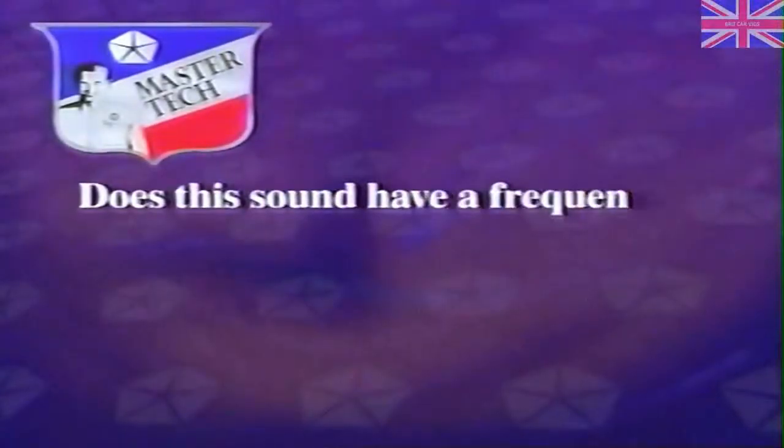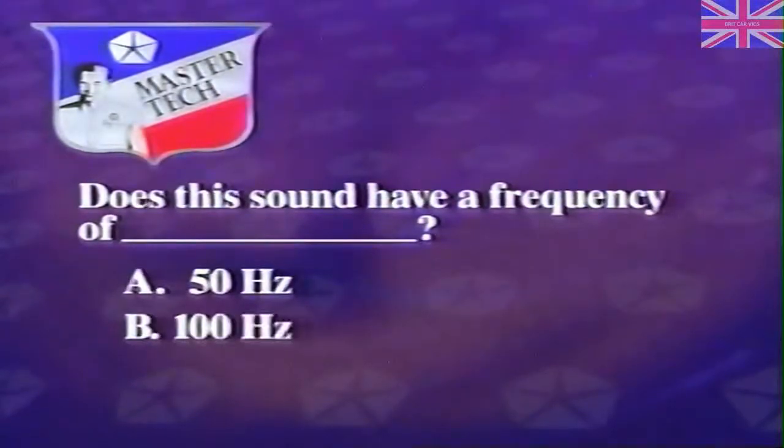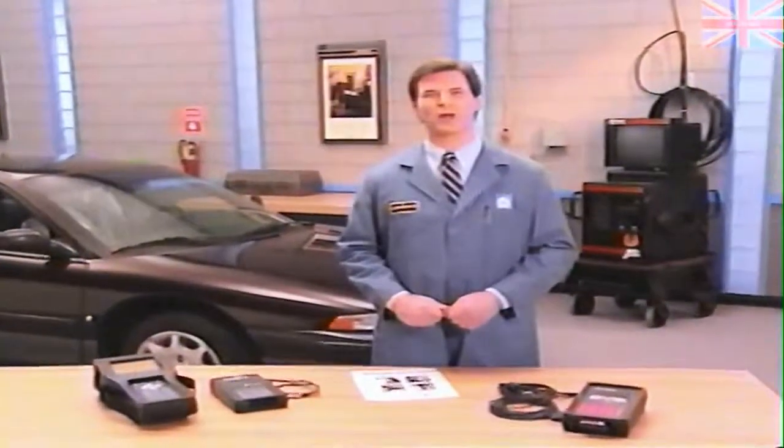Let's test our abilities. Does this sound have a frequency of A, 50, B, 100, or C, 200 hertz? If you said C, 200 hertz, you are correct. Your ability to recognize vibrational frequency levels is important when determining which components are causing excessive noise and vibration. We'll demonstrate this later on during step 4 of the troubleshooting process.